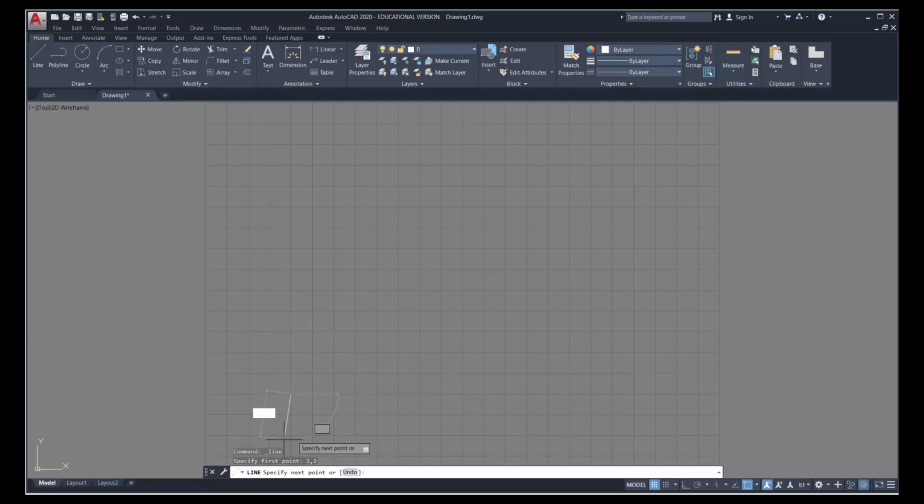And I can move my mouse around, and it shows me all these different values, angles, and direction and all that. Well, I don't want to use this in absolute values. What I want to do is type in the position. And this is something that we would actually use, for instance, like I mentioned earlier, in surveying. Now, to remove these indicators that are on your screen, simply press the F12 key that's at the top of your screen, and you'll notice that that should all disappear. And now when you move your cursor, the line doesn't have the angles and the direction and all that.